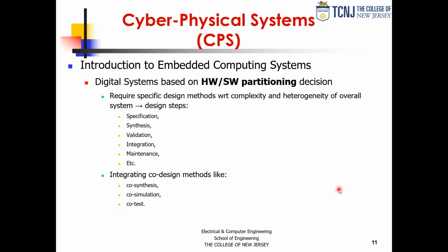And I want to talk in terms of a system that has everything. It has software, it has synthesized hardware in the form of, let's say, an FPGA, programmable logic fabric, and it also has a processor where you write software for that part of the system. So you have the three parts. You have the core, say an ARM core, embedded in a sea of programmable logic in an FPGA, and that is the start of your embedded system. You can have more things outside of it, but you have the software, the core, and the programmable logic.